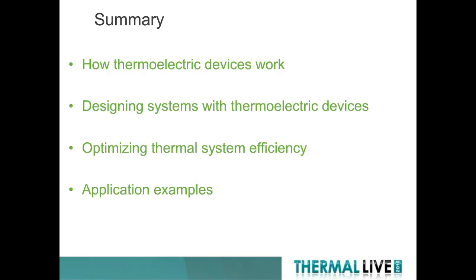Also, a big concern with that, again goes to thermal grease selection, is pump out during thermal cycling. You'll see that there are plenty of very reliable options out there, and you will see that the suppliers of those materials advertise low pump out.